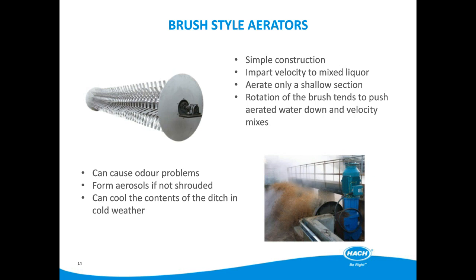Another drawback of these aerators is that they entrain atmospheric air, which in severe weather conditions can significantly cool the body of water, despite the amount of energy being put into the system. This is in direct contrast to diffused air systems, which tend to heat the body of water. Some sources state that up to 4 degrees centigrade of cooling of the body of liquid by evaporation is possible. This cooling effect can have a significant effect upon the nitrification rates in the winter months, when temperature of the liquid within the ASP is already reduced.